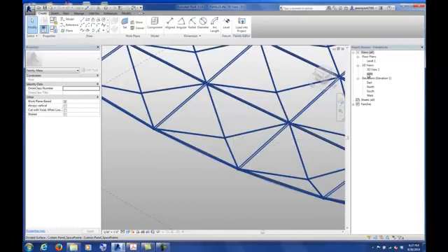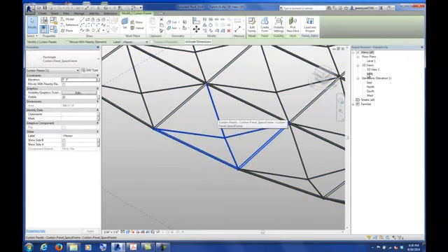So I never have to physically go in and type in, well, I want this pipe to be 3 inches, or I want the other one to be 6 inches, and even some of you might have had that problem getting the pipe to change throughout the homework assignment. Since I'm already in this file, I can tab over to my curtain panel and select it by hitting the tab key a couple times and then left click. When I do that, it allows me to edit the family, so I can click Edit Family up here at the top.